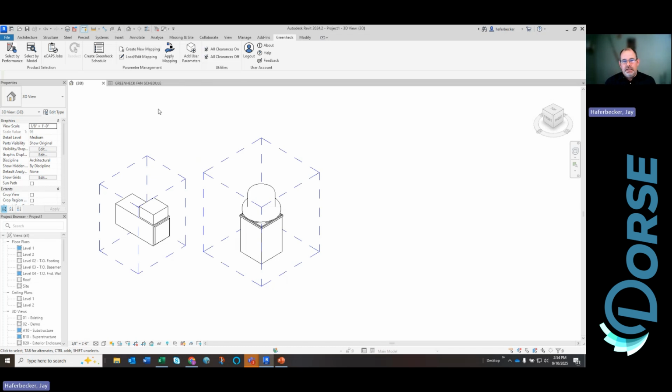Now, the third technique is the opposite of the second technique. Remember, in the second technique, we're taking the values from our parameters and putting them into your shared parameters. The third technique is we're going to take your shared parameter and put it into our Revit family. The use case there is, maybe you have a BIM department that says, hey, you can only use these certain Revit families. And most likely what they did was they took some manufacturer and just stripped out all the parameters, making it basically an LOD 200 family, right? Which we already have an LOD 200 family over here, right?